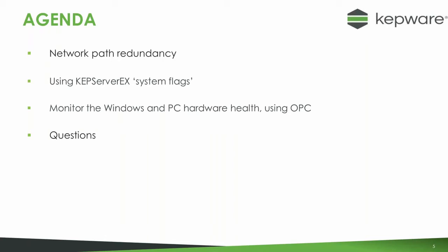Then we'll be looking at the system flags in KEPServer, which can be very useful for diagnosing faults and monitoring the status of a system. And then we'll be looking at a driver within KEPServer, which is called the system monitor driver, which is useful for monitoring the system, the OS and the PC hardware.